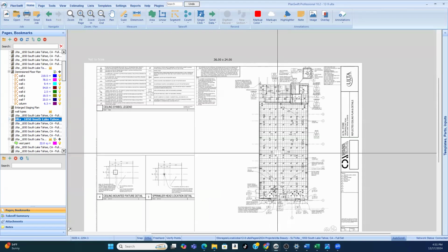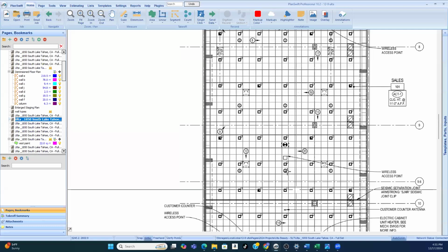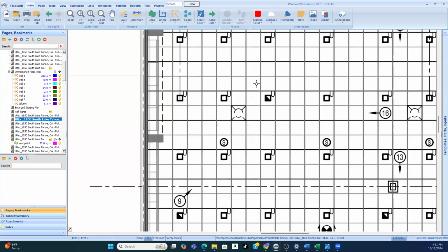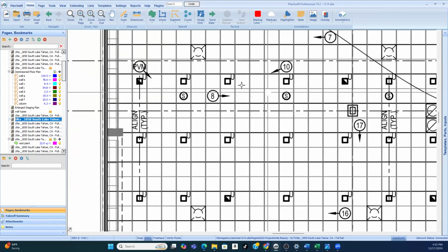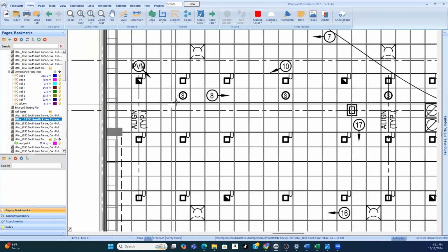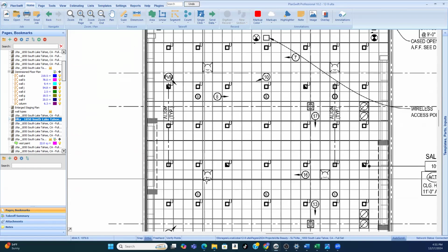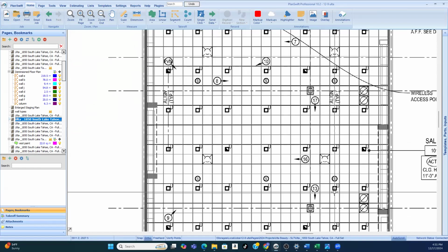And so the reflective ceiling plan, they call it that because it reflects or shows you every component on the ceiling. But it's meant for the ceiling finish only. Okay, so it'll show you where the lights are. I'm sure these are some kind of electrical, the lights, the smoke detectors is showing us. It's showing us the supply grills. Okay, and it's only for the finish trade.